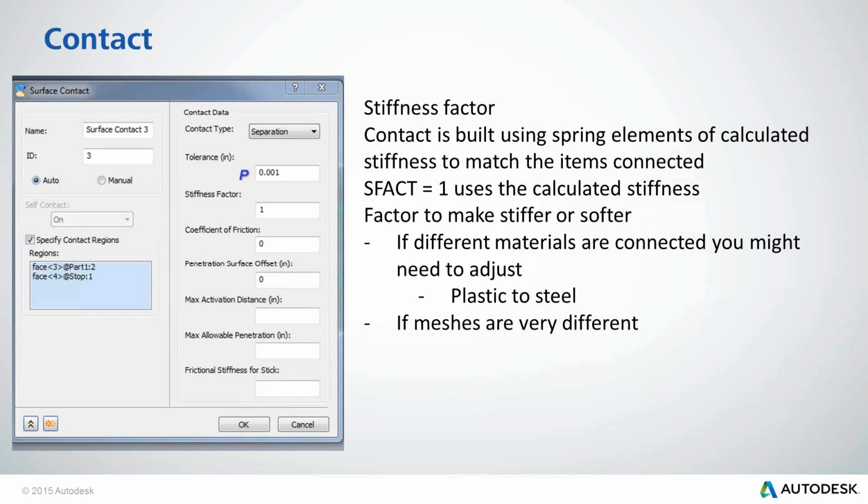You can also write out the text file, the Nastran deck, and edit it on your own, either in a text editor or the Nastran interface, where you can edit the deck and launch analysis as well. But the In-CAD itself is basically a user interface built into Inventor and SolidWorks. Today we're going to be working inside of Inventor.